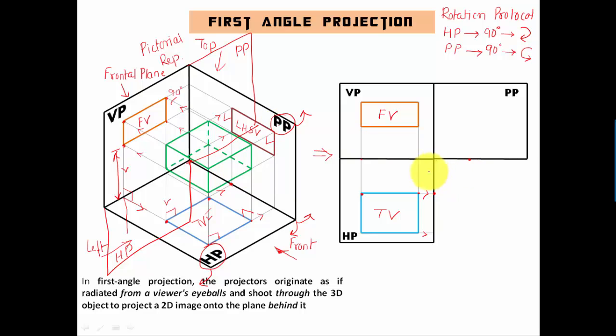And these distances, this distance I'm talking about and this distance, appear as if both of them are equal. Now when both these distances are equal and this angle is equal to 90 degrees, you're gonna have a line over here at an angle of 45 degrees. So what you need to do is draw a line over here at an angle of 45 degrees, and it's going to look something like this.